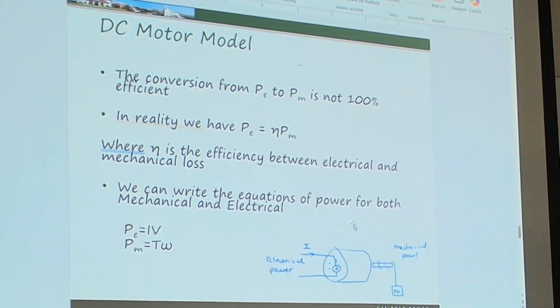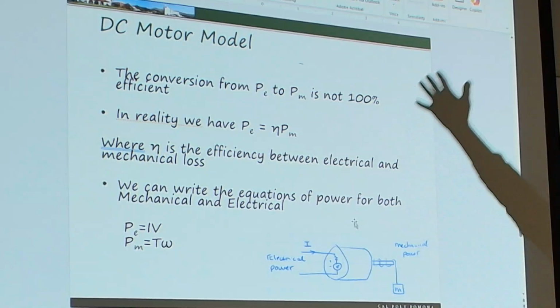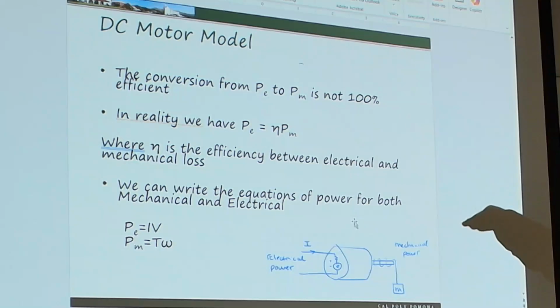But what is that going to do? The faster that is being turned, what is being generated higher? The back EMF, right? So have you ever noticed when you plug in a motor, it starts to get faster, right? But theoretically, it should continue on because if you know the Laplace transform of that motor, it's 1 over S, which is an integrator. Which tells me if I apply voltage, theta should be incrementing and theta dot should be incrementing into infinity. But it doesn't. It stops. It gets to a steady state, doesn't it?